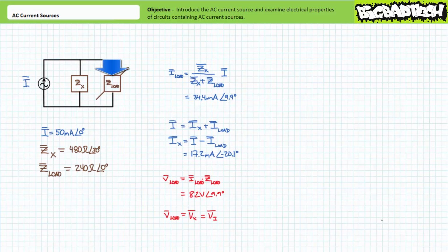Current with a larger magnitude is traveling through the smaller magnitude variable load impedance. Conversely, current with a smaller magnitude is traveling through our larger magnitude fixed impedance. It makes sense. Accounting for phase shift, the summation of both outgoing current paths equals the incoming current. We can be reasonably certain our results are correct.